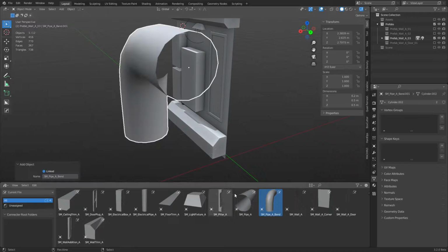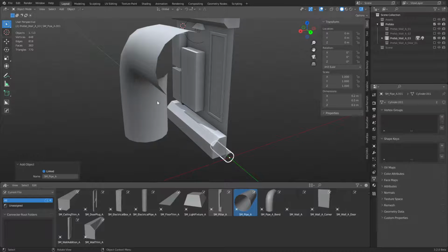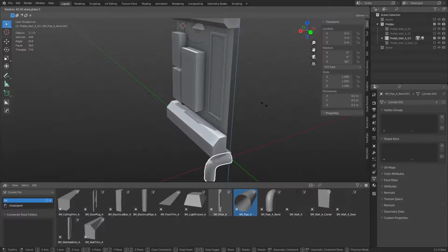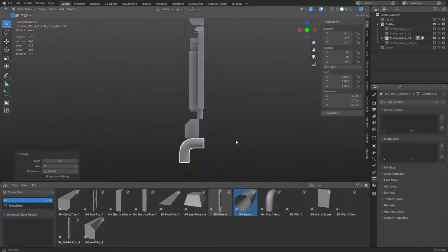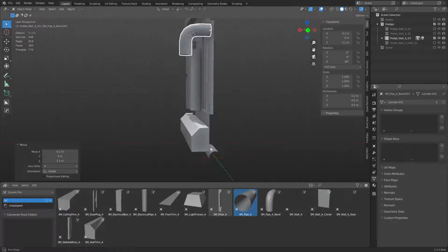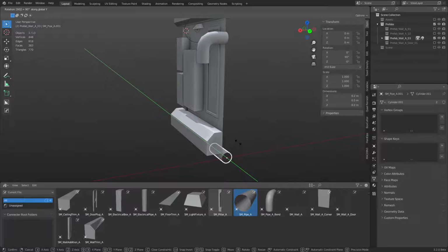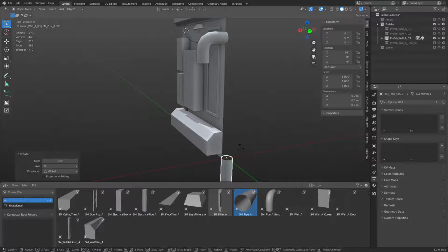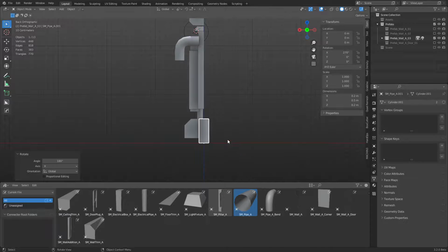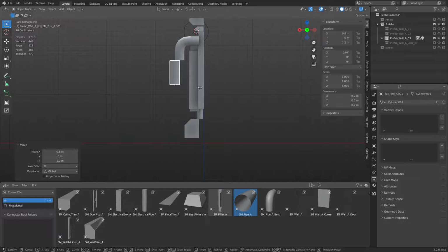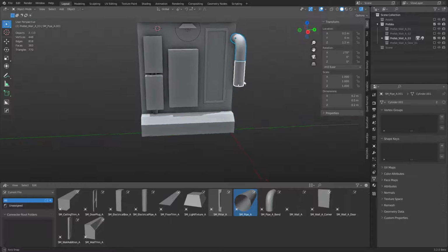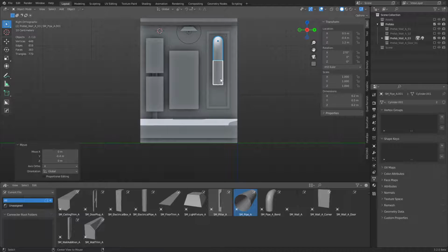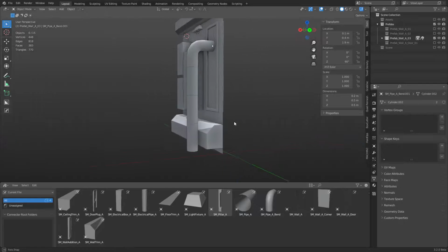Now, I want to make these pipes here real quick. Let's just drop them in. Once again, they came in way too close, but I'll rotate this one 90 degrees. This is going to be kind of fun, but rotate this 90 degrees the other way. So you see these snap together now, right? Using the grid. That makes life a lot easier. Because if I take this one and duplicate it or instance it, so Alt D, and run it down to the floor for the most part, no problems. Something like that.